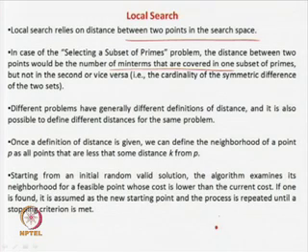The points in the solution space are subsets of primes. Now, you have to define a distance, and distance can be anything. One parameter can be the number of prime implicants or the number of literals in the prime implicants. If one point has 100 literals and another also has 100 literals, you can say the distance is equal. But if one has 100 literals and the other has 50, the distance is 50.